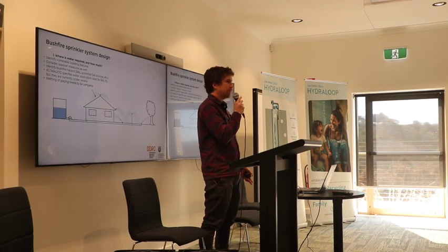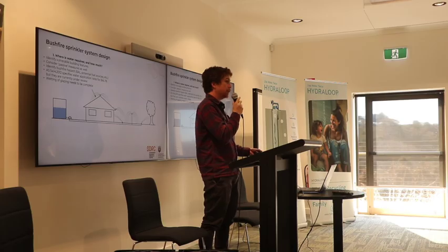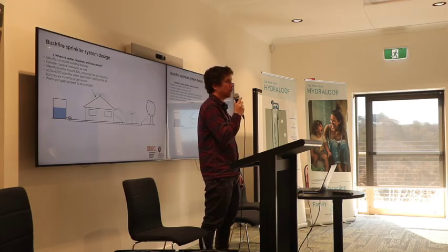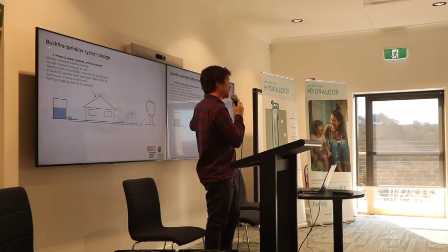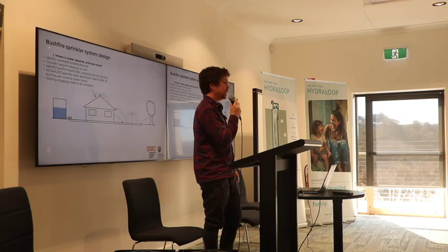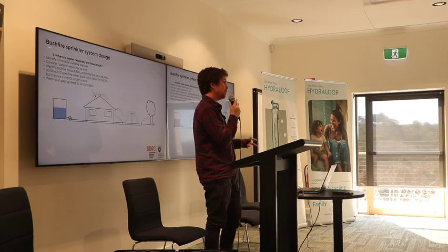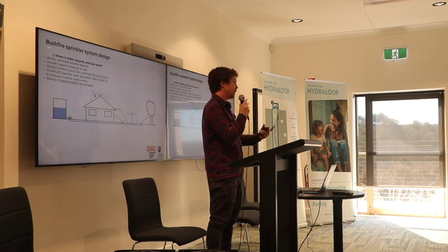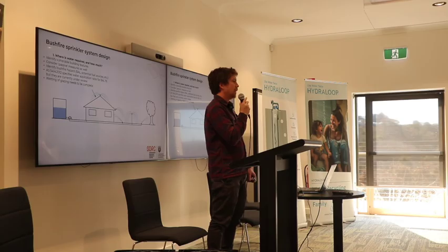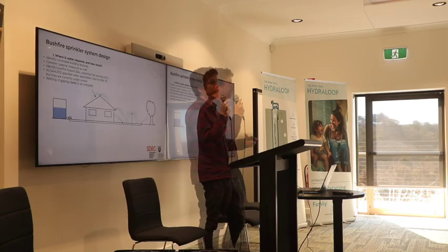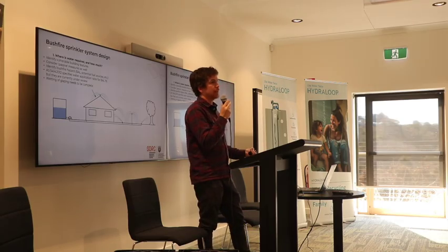What you really don't want is to put in a bushfire sprinkler system and then feel like you have to stay and wait later than you should be before evacuating so that you can activate the system. That's something you really want to avoid. So some of the science backing up the design of these systems is still evolving, and we don't know things with much certainty, but what we do know with certainty is that if you're designing these systems, you should have an independent water supply, and you should have pumping capacity or a gravity-fed system, which is going to operate without power as well. It's in the hundreds of thousands of litres.